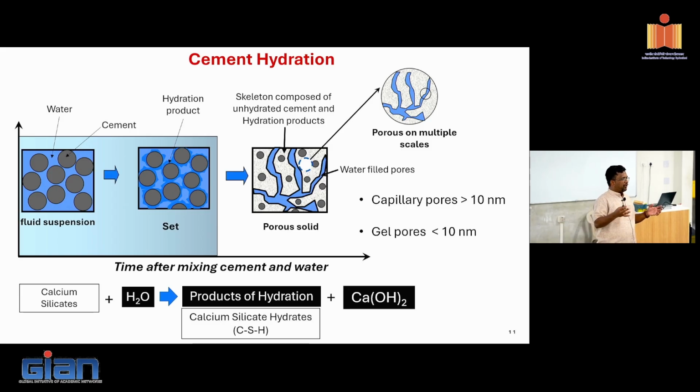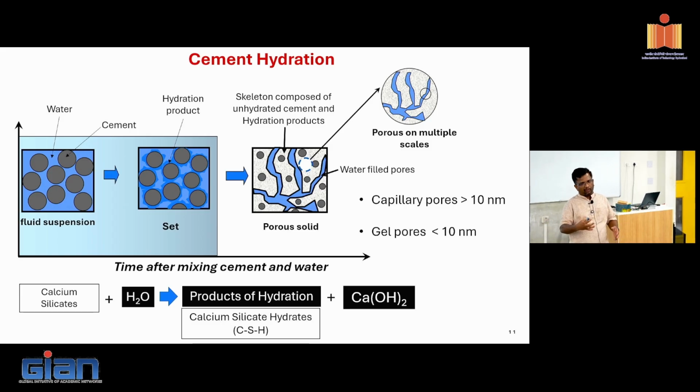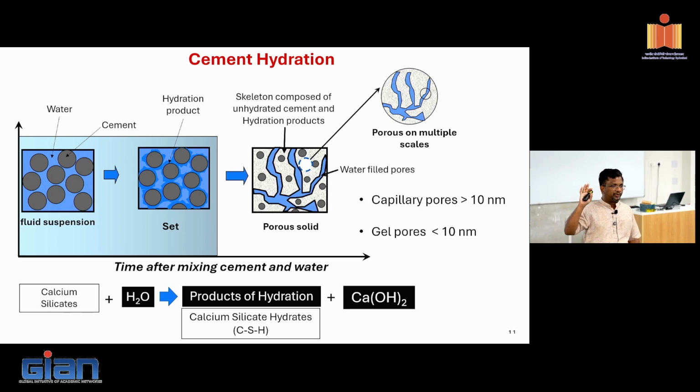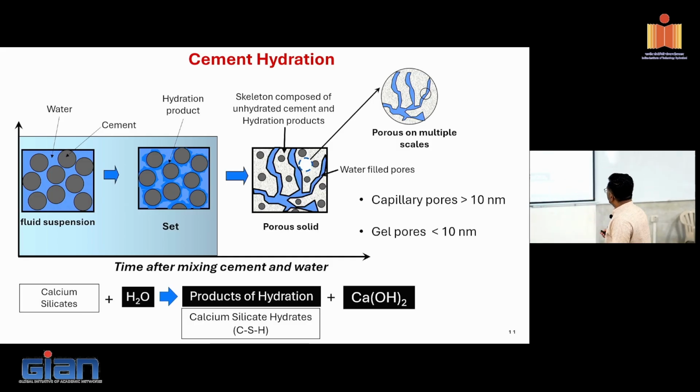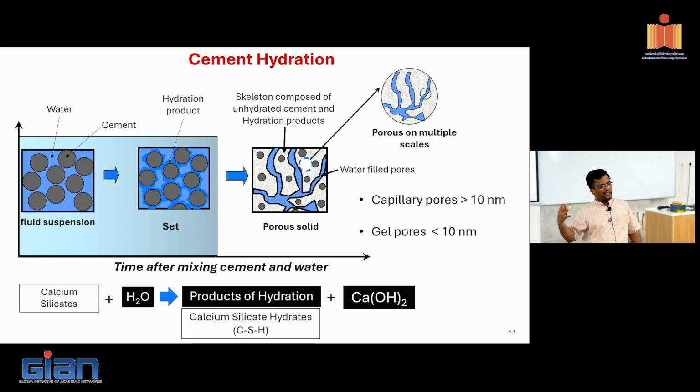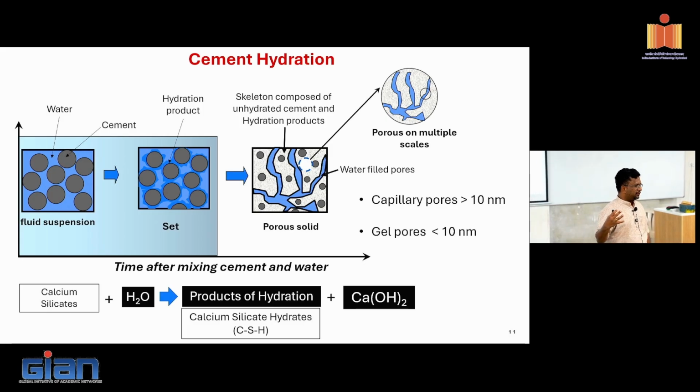So capillary pores actually create the passage for the water to escape out of the system. Now I told you, where does the major durability concern come from? It comes from the excess water that is in the system. It is trying to escape out of the system, right? So if I have more capillary pores, more water can easily go out of the system, which we need to be careful about.